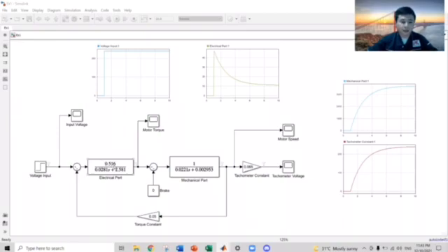0.516 is the EMF constant, the voltage induced constant, 0.0218 Henry is the armature inductance, and 2.518 ohm is the armature resistance. The second transfer function block has 0.221 kilogram meter square, which is the moment of inertia of the motor, and 0.002953 Newton meter second for the viscous frictional constant of the motor, Bm. Here is the tachometer constant, and lastly, we have the constant.